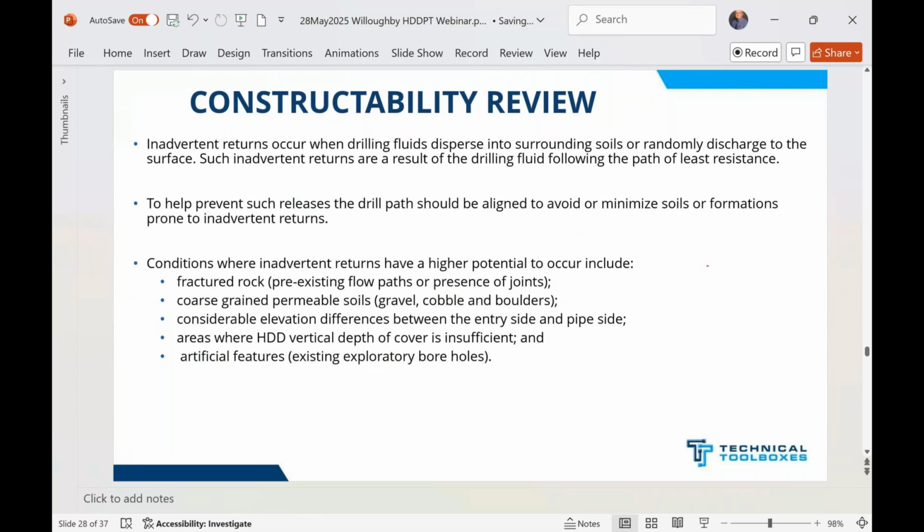On the pullback side, 8 degrees is usually what we'll use for most pipes. The bigger the pipe gets in diameter, the smaller you want that to be. Remember, when you come up out of the hole at 8 degrees, the contractor has to pick that pipe up and get it coming back down that hole at 8 degrees.